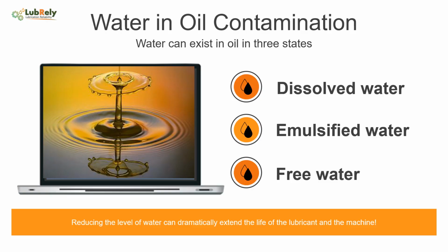The point at which an oil contains the maximum amount of dissolved water is termed the saturation point. At that point, the water is suspended in the oil, in microscopic droplets, known as an emulsion. This can be compared with fog on a cool, spring day. The saturation point has been exceeded, resulting in a suspension of small droplets of moisture, also referred to as haze.